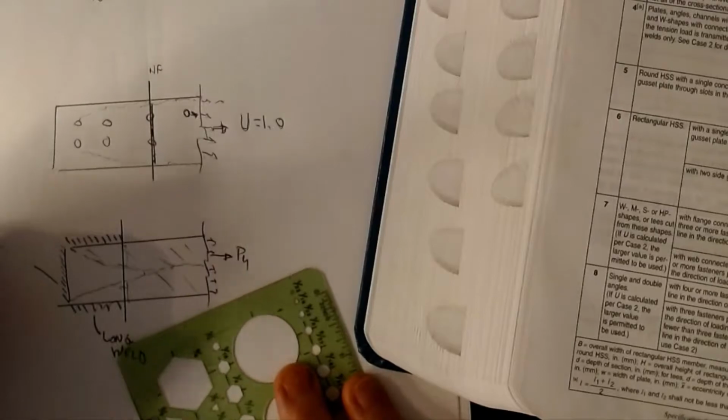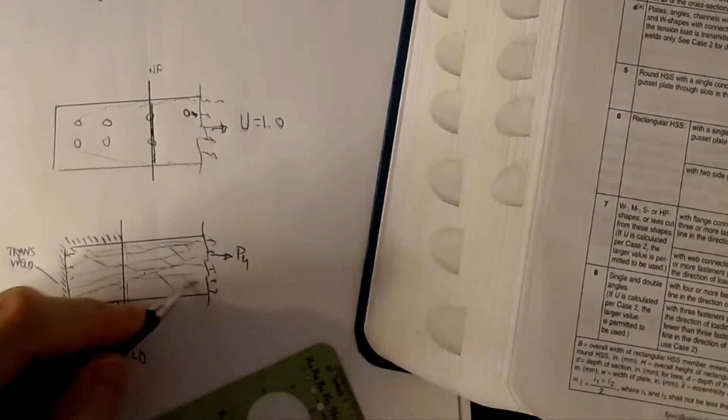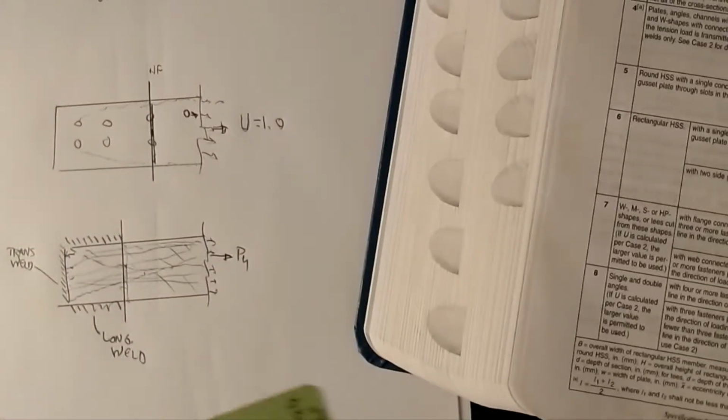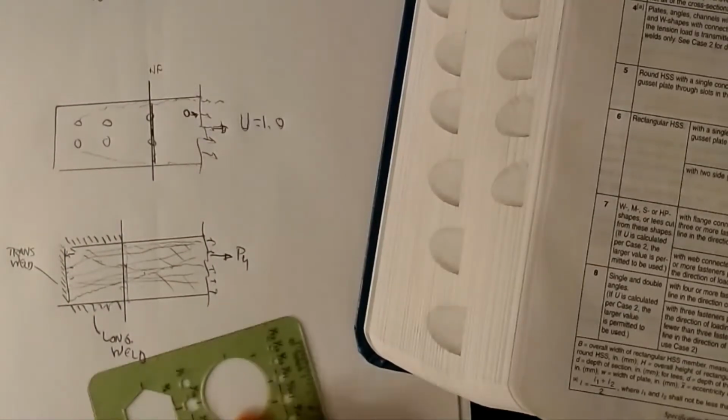Okay, but if we come in and were to put in a transverse weld on the back end of this thing, this is a transverse weld. And again, their orientation is based off of the orientation of the load. So a transverse weld goes across the load, or perpendicular to the load. A longitudinal weld is running parallel to it. Now this arrow, it's going to here, but it's also going over to here, and it's coming over to here. And now what you've done is you've started to load the entire cross section much more effectively. You can see that the dead zone, now we've recaptured the capacity and put that guy to work for us just by putting in a simple weld on the back side.